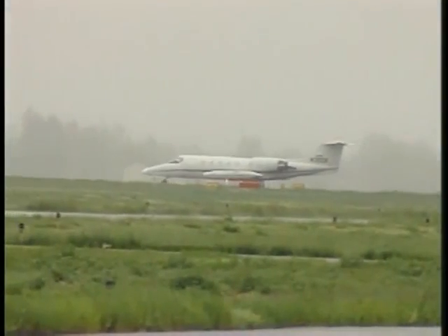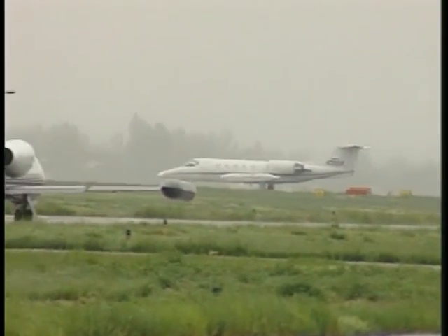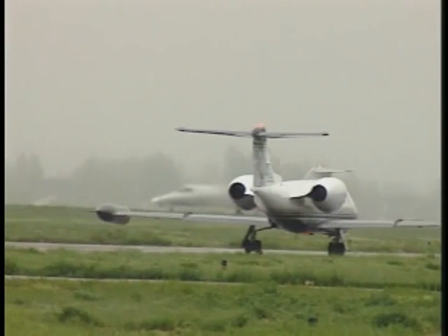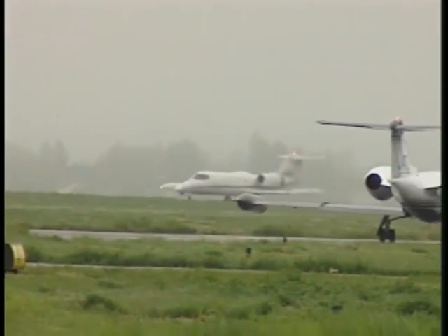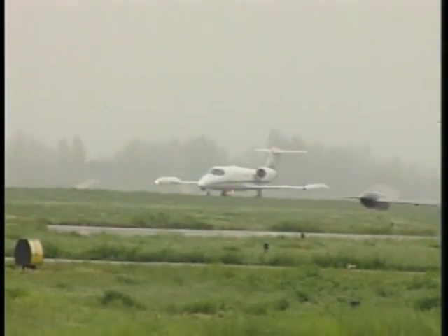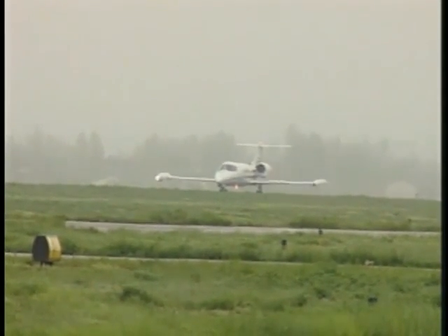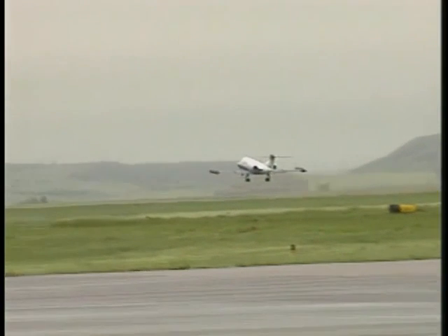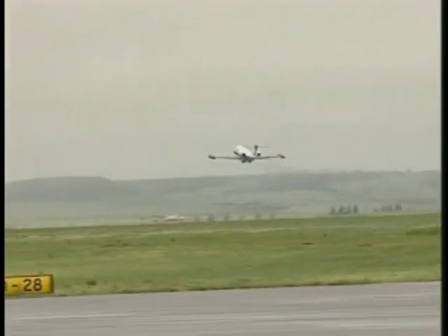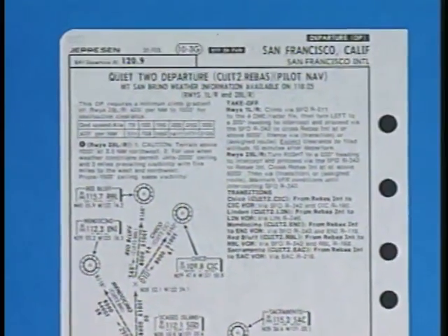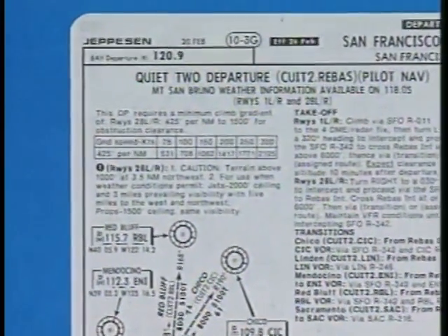In addition to providing obstacle clearance, at busier airports, instrument departure procedures, or DPs, expedite the flow of air traffic by reducing the length and complexity of issued clearances and by cutting down on pilot-controller communications. As with any IFR departure, DPs also assure adequate obstacle clearance. Some instrument departure procedures contain specific performance requirements in order to maintain adequate obstacle clearance.